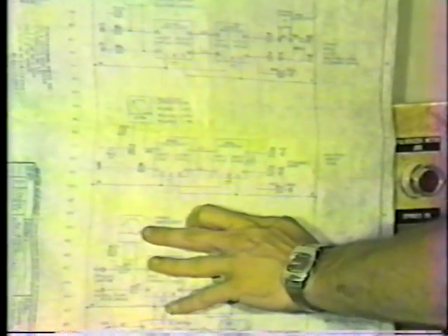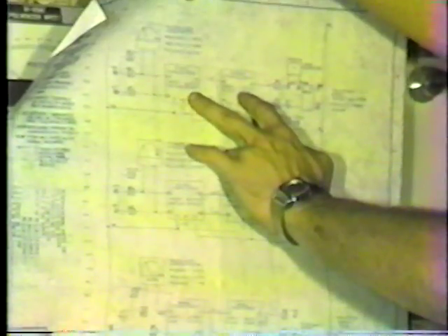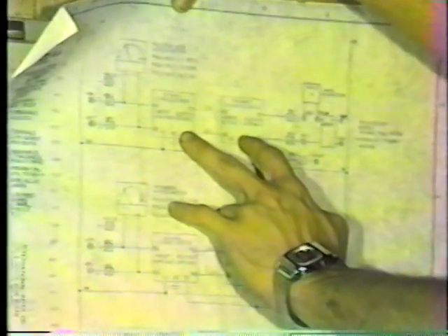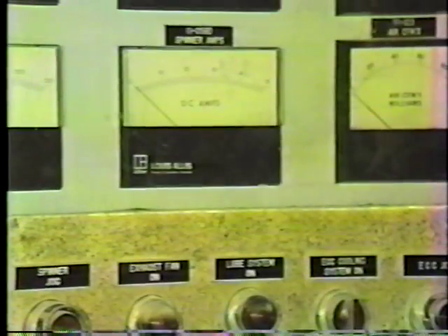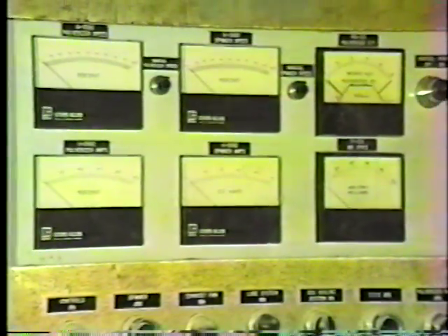This drawing covers the pulverizer speed meter, spinner speed meter, pulverizer current meter, and spinner current meter. And we have our signal conditioners taking a 0 to 40 volt signal, converted to a 4 to 20 milliamp signal for the computer to read, for each of the 4 signals. Do you want to show me those units? All right, point them out to me, please.